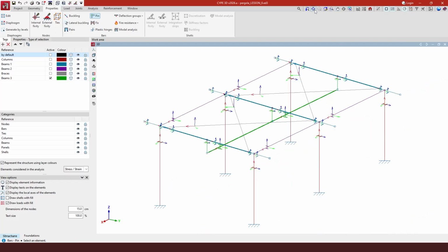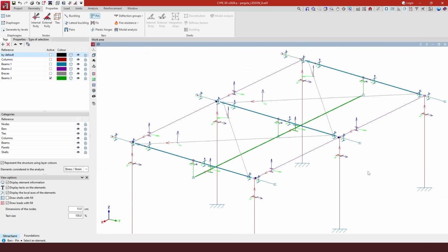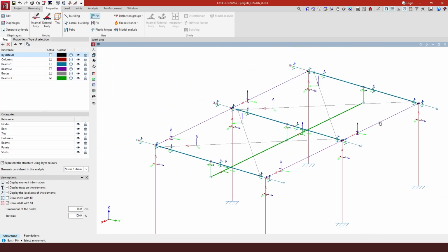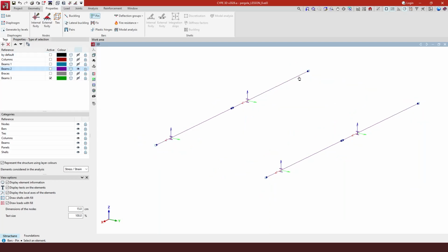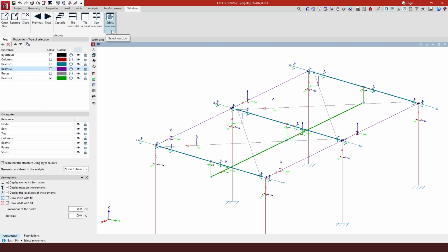If I zoom in on this other bar, for example, that we also have to pin, if instead of clicking in the middle of the bar, we click more towards one end, we will have control over which end we're pinning, but just that, not what value nor what plane we're pinning. And in our case, all these 4 bars that are part of the BIMs2 tag should be completely pinned. We're also going to pin the braces in the roof.